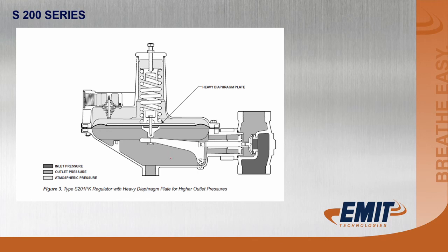Very common regulator here, 200 series or 300 series, either one. Good stable regulator. They tend to wear out a little faster than some other regulators. The wear points are right here. You'll see that worn out right there, and as that wears out, the regulator will become less and less stable because that doesn't slide as it goes up and down to regulate the fuel.